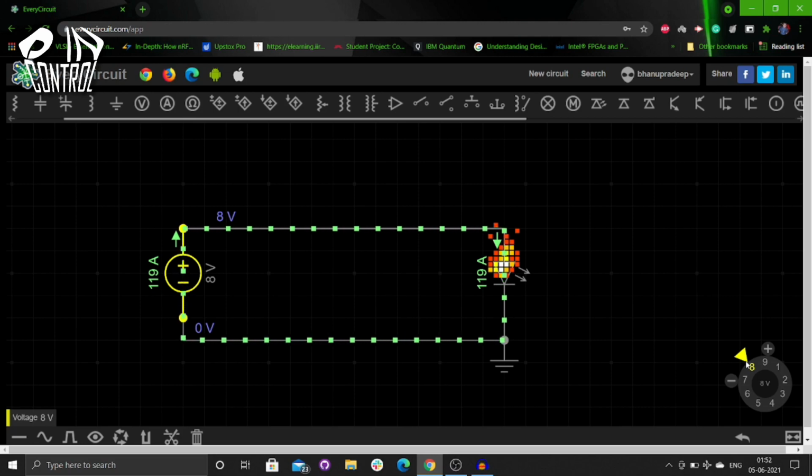So when you are giving more voltage and you require less voltage for this element, we use resistors to decrease the voltage from a higher voltage to a lower voltage. Let us see the second part, connecting the resistor in series with the voltage source and an LED.